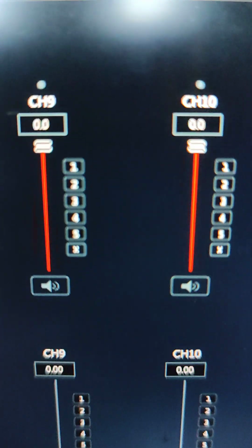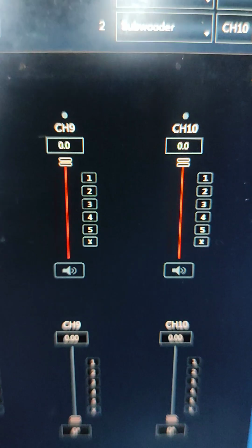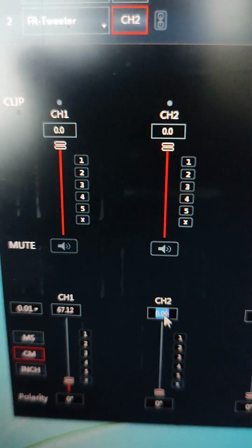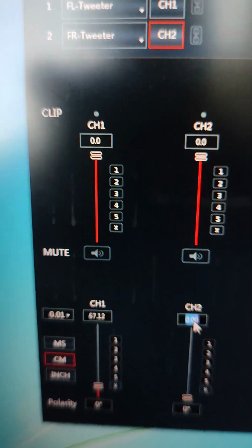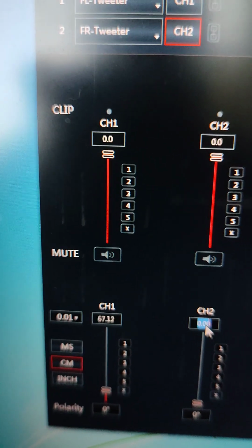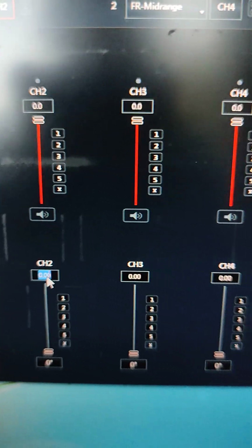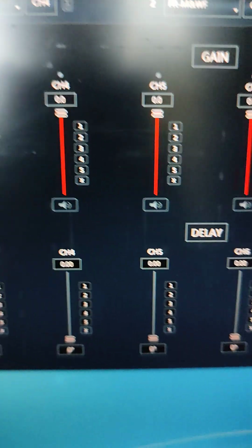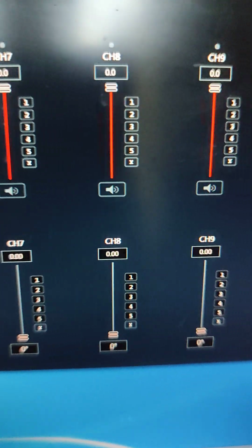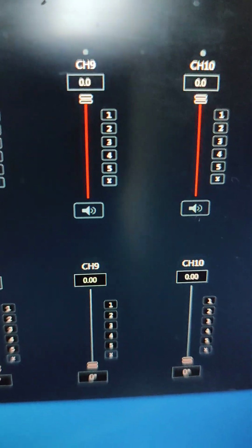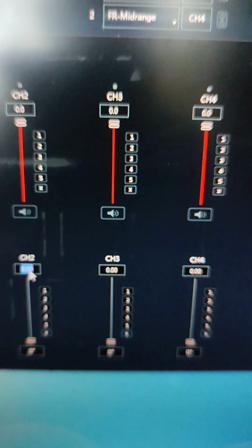I would actually raise the SPL on channel 9 and 10, your subwoofer, by 10 dB. So I would set all of the speakers at 85 dB, pink noise at the head position at the driver's seat. Then you know your time alignment is right and your center will probably be quite accurate. And then if the SPLs are the same, if not, you just touch them up. I would go 10 dB more on my sub, and then I would get quite a natural curve, and then it'll be quite good sounding.